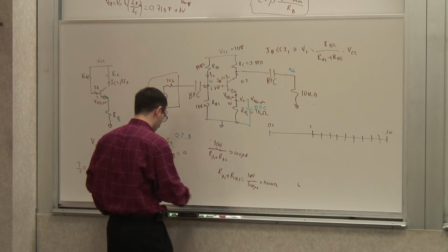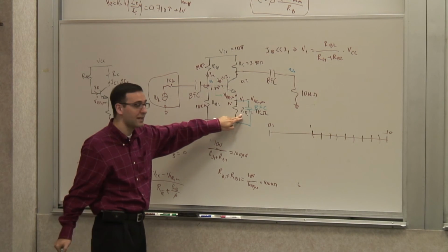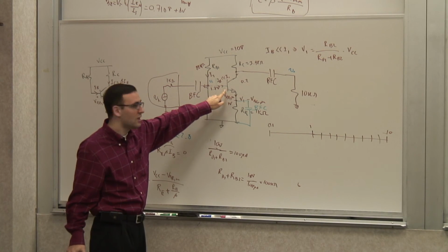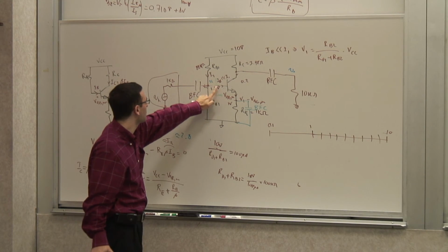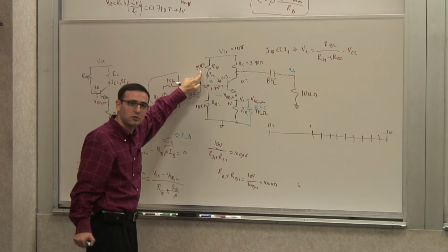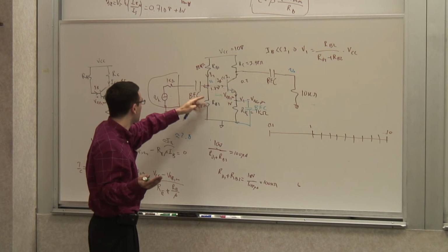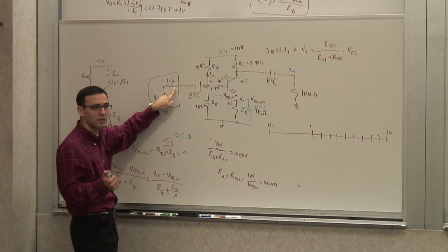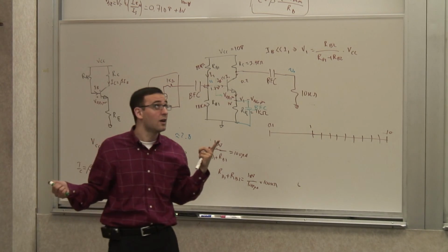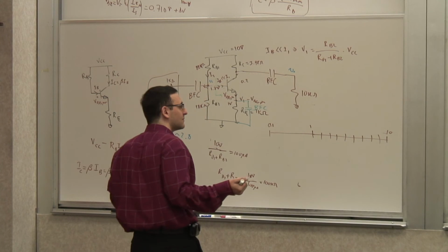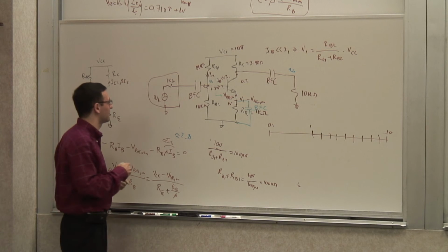This impedance is changing now, because it's not beta RE anymore. It's just R pi. So now instead of being about 100 kilo ohms, it's about 2.5 kilo ohms. So it's 2.5 kilo ohms in parallel with 18 kilo ohms in parallel with 82 kilo ohms, it's probably about 2.4 kilo ohms. It's almost 2.5. So it's a voltage divider between 2.4 kilo ohms and 1 kilo ohm. That's about 2.4 divided by 3.4, so that's probably about 0.6. No, it's actually more. It's more like 0.7.